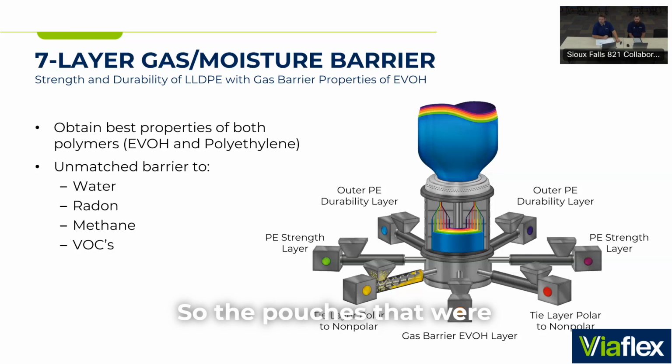So the pouches that were made to contain these cubes, as Chris mentioned, were fully submerged in gasoline. I believe the ones on the bottom were on the order of months. And as you can see, there's very little deformation of those geofoam blocks compared to the others. Primarily, that's likely coming from the welds, as they were a PE to PE weld, so they're going to allow some level of transmission in that seam, but there's almost no damage to those blocks.